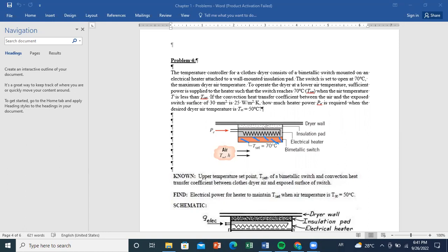So we are giving energy to our system in heating form, because we are transforming electrical energy to heating energy. And then this energy is convected outside. It's lost by the system because of convection with air. So all we have to say then is that the electrical heat will be convected out, so P_E is equal to Q convection.